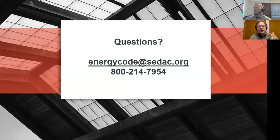A daylight sensing commissioning question with regards to window treatments. The code does not restrict window treatments from being used. However, during the commissioning, the window treatments would need to be in their full open position to commission the system properly.